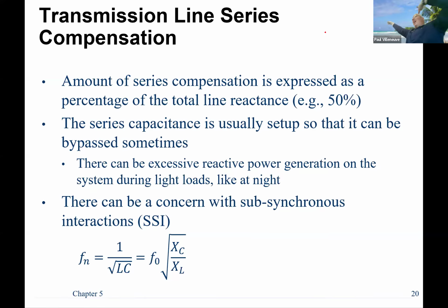But over here, I've reduced the effective value of X. So I'm not even getting a lot of reactive power for a series cap. It's just that that value of X has dropped. So my V1 times V2 over X value goes higher. But yeah, shunt ones usually just increase the capacity of the line, because your magnitude of current can have more real power associated with it.